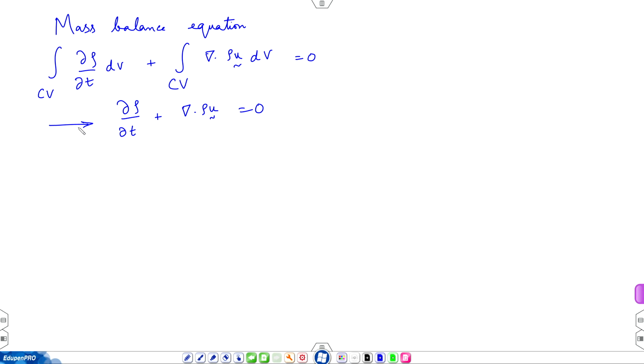What is the physical interpretation that we have discussed many times earlier? Just tells you that inflow minus outflow, or let us say mass inflow minus mass outflow, will contribute to changes in density in the region being studied. Here the region is a point interpreted in the continuum sense.